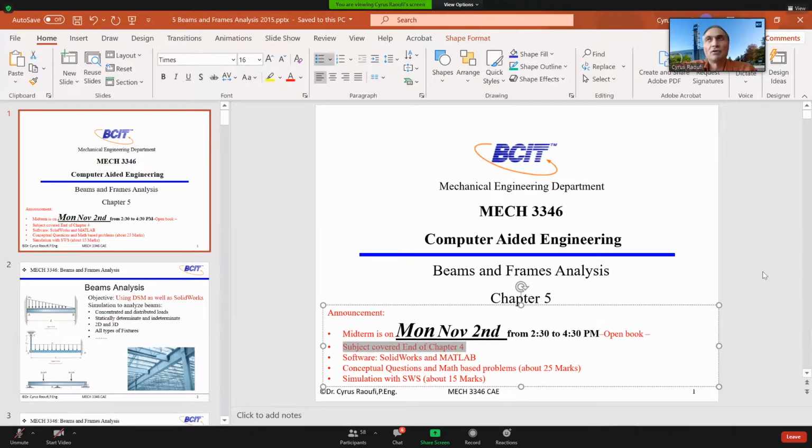And then you are going to construct the displacement vector, and since we are dealing with a one-directional element, you need to construct the displacement matrix such that each node has 1 degree of freedom, and you're going to look at either the y-axis or the x-axis. You're going to look at the displacement at those nodes. And those are F equals KD, the F part and the K part are done.